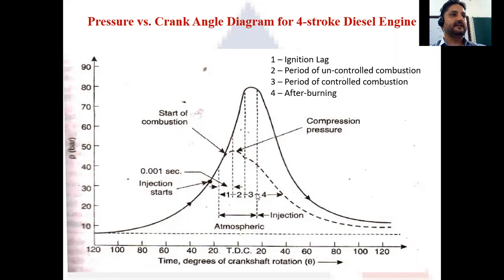So phase 3 is the period of controlled combustion. The fuel that is injected will burn, and this peak will be reached. This peak is the maximum pressure peak.